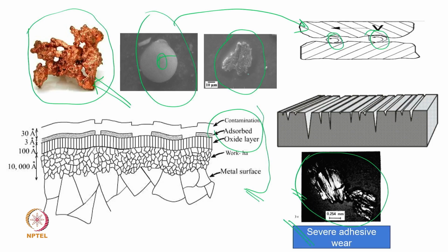As I mentioned, this is a plate-like debris, so it will be a kind of adhesive wear. Sometimes we use the word spalling, and this is much bigger, because this one is 10 micron, while this is 254 micron. So, naturally this size is much bigger, and we say size matters, shape matters, number matters, chemical composition also matters. So, these 4 characteristics are required for analyzing the wear debris, and that gives good information to us.